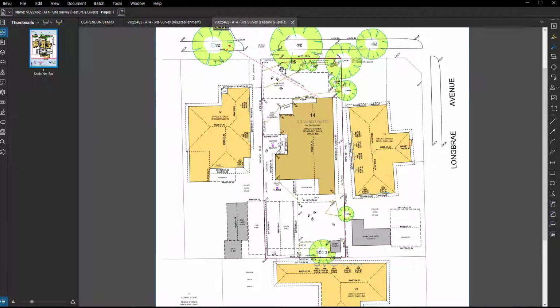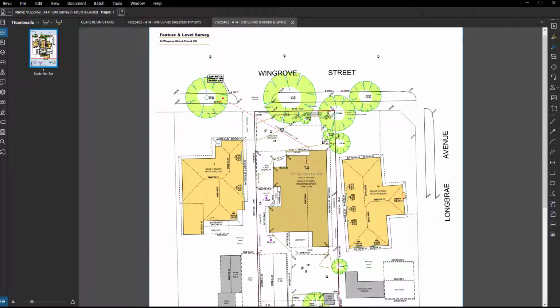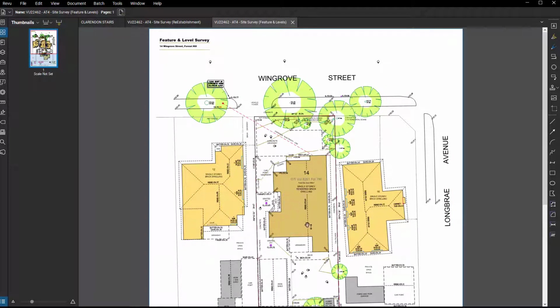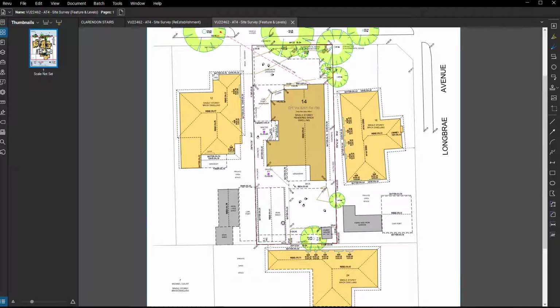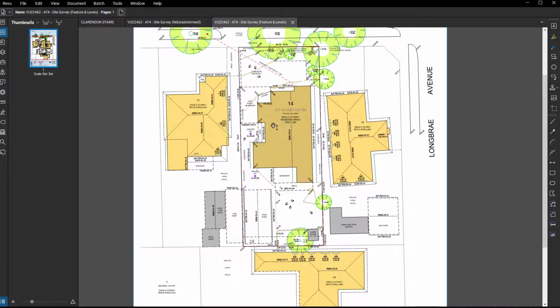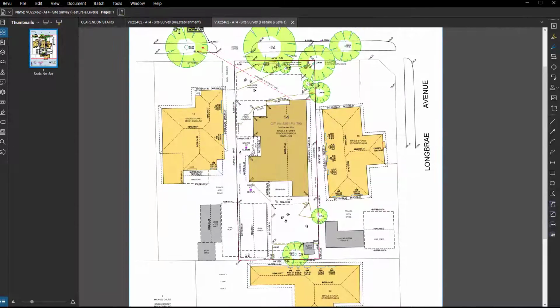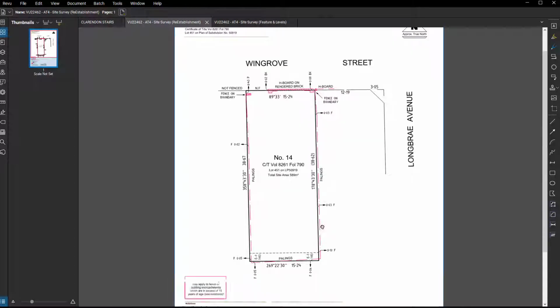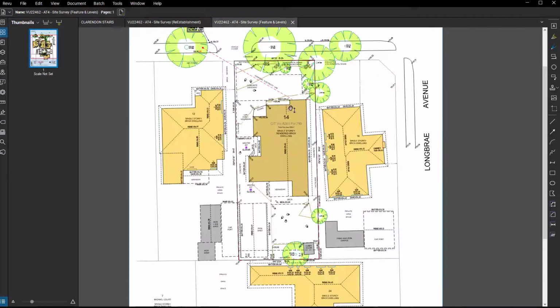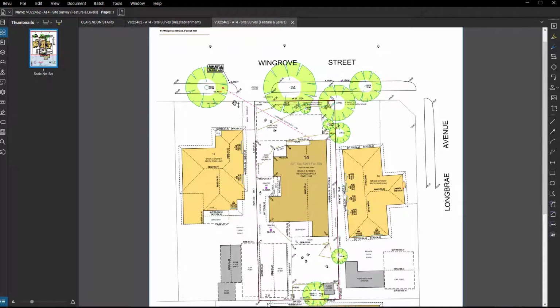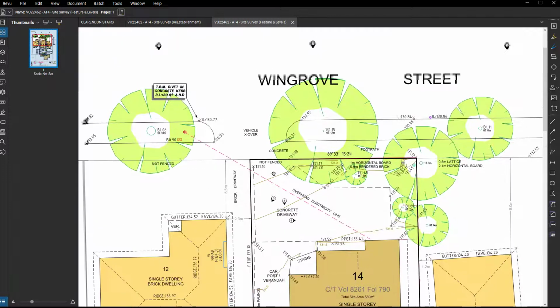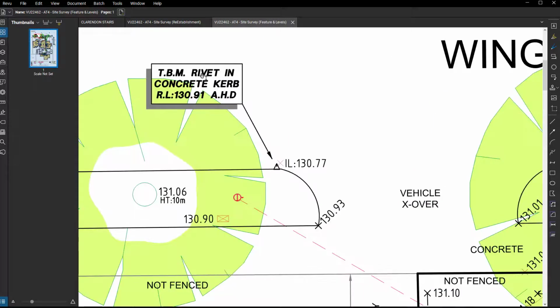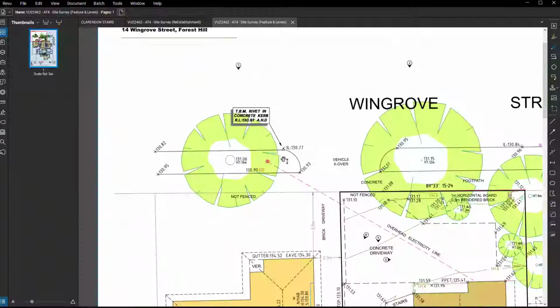So we're taking this site. This is the site that we're using in Forest Hill, with this house here, and Jackson's done a lot of work for you in terms of CAD files. This is the site establishment survey, giving us our boundary, and then this is our site features and level survey. The survey is pretty good. It's got almost everything we need. The only thing it doesn't have is that it has a temporary benchmark which gives us our height datum, but no coordinates. I really wish there were coordinates here.